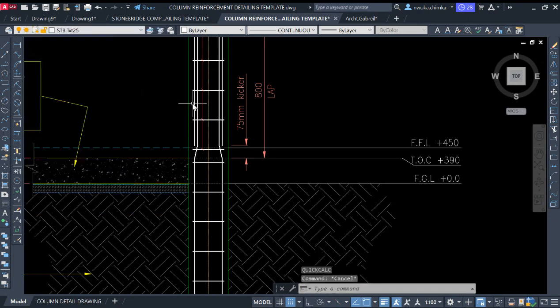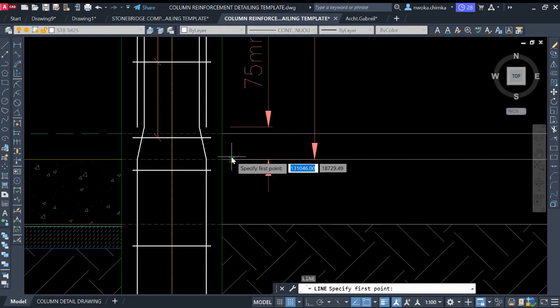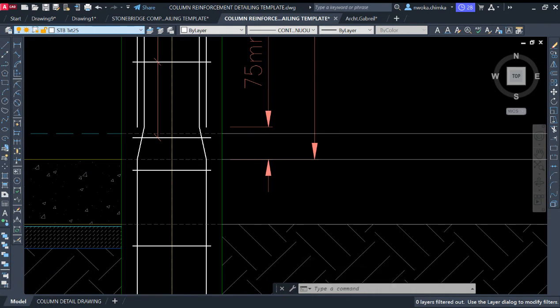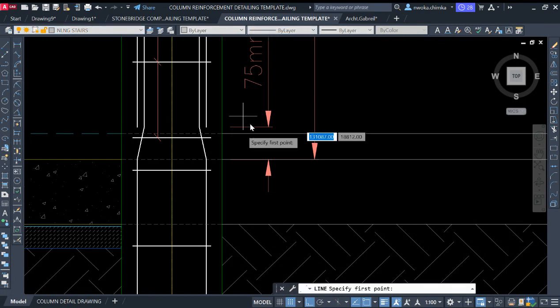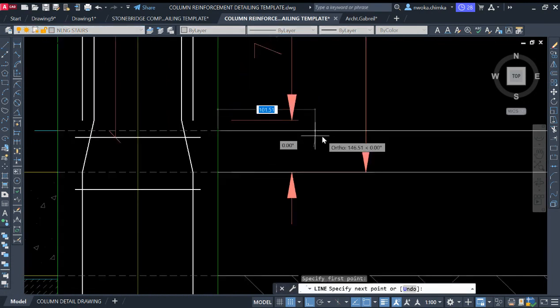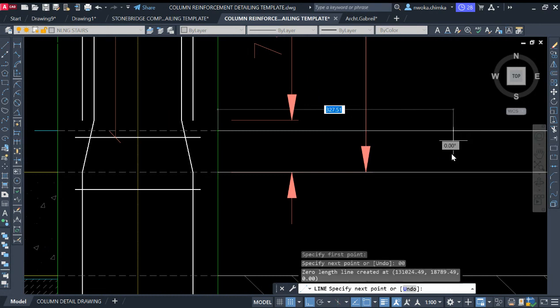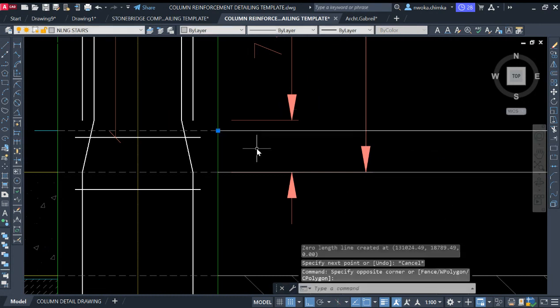So I'll go and hold the line and then go right like this. First of all, I'll have to change the color. Let me use this color for step. I think we have step here, staircase. Yeah, we have staircase. So I'll click on this, change this to super layer, and then click on this and change this. I have to put my step width of 300, and then click Enter. No, step width of 300, sorry.